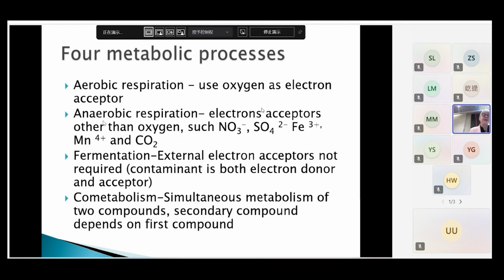Then if it seems to be feasible, try to look at the economics of using that particular type of remediation. Then you could go to very small tests, what we call pilot tests, where you'll just take a small section of your contaminated area and do some testing at that particular area. So you can then test out some of the design procedures at that particular site.